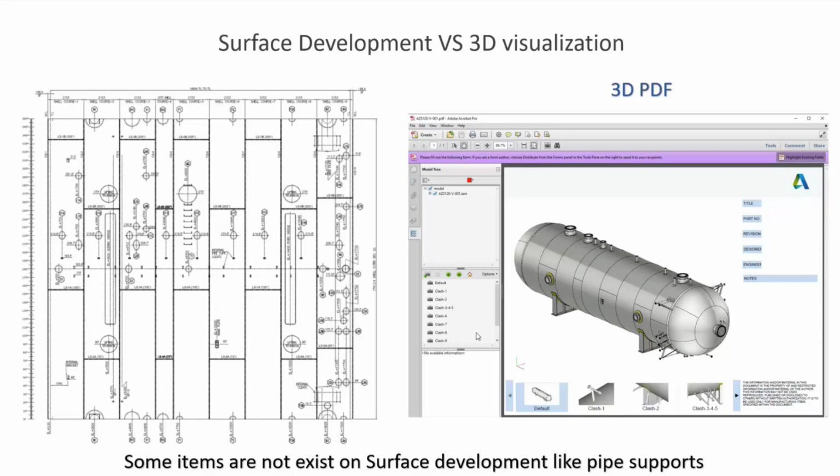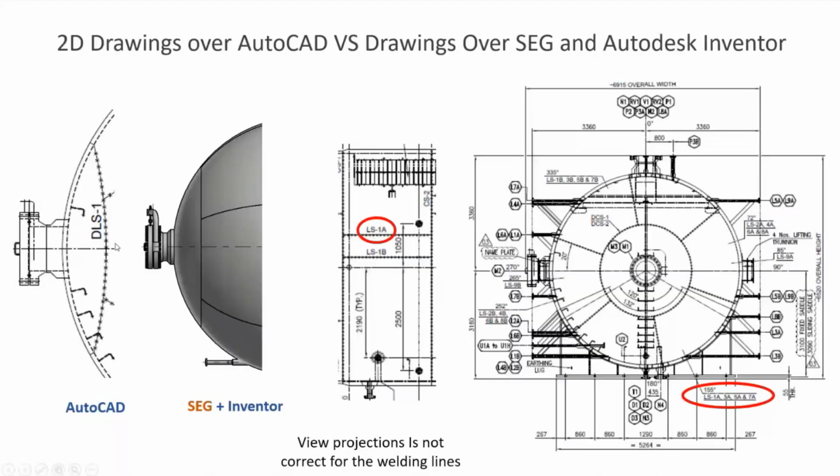Okay, in this drawing, as you can see, the welding line on the head takes this convex direction, but actually it's a straight line. So in some views from the draftsman, he may not calculate the projected view in a correct way. So it may affect your drawing.